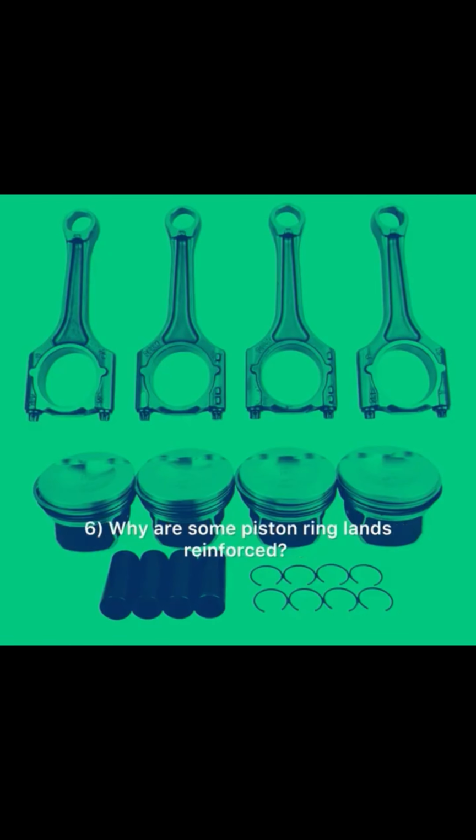6. Why are some piston ring lands reinforced? Control heat expansion. Reduce wear. 7. What are the types of piston pin designs? Full floating. Press fit. 8. What are the functions of the piston rings? Seal against gases. Control lubrication. Transfer heat from piston to cylinder wall.